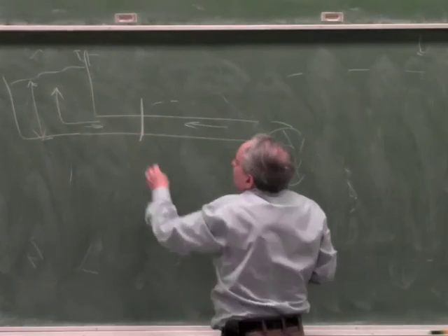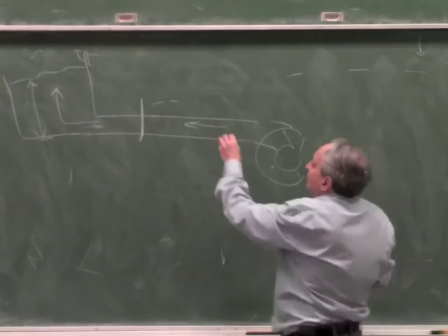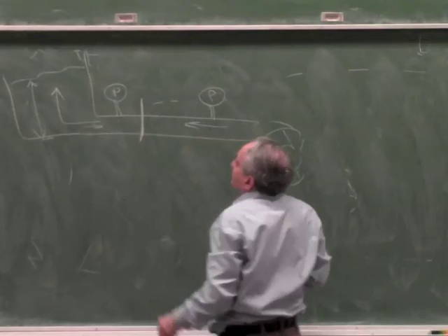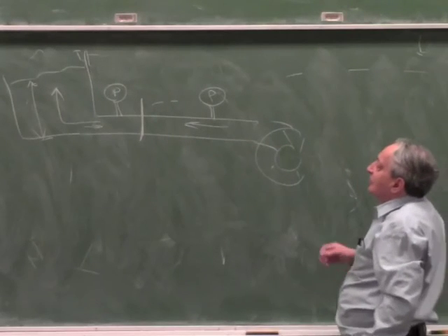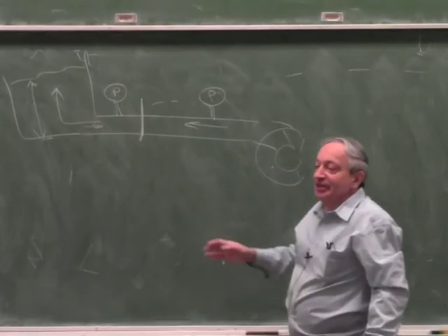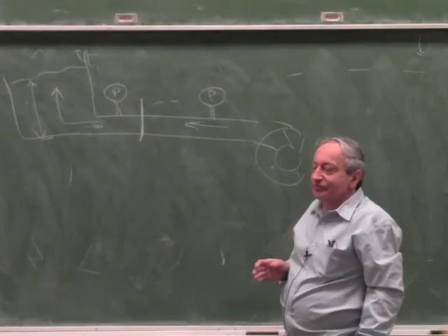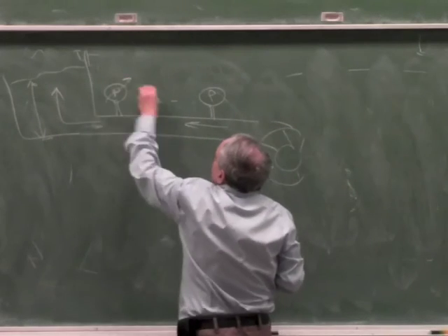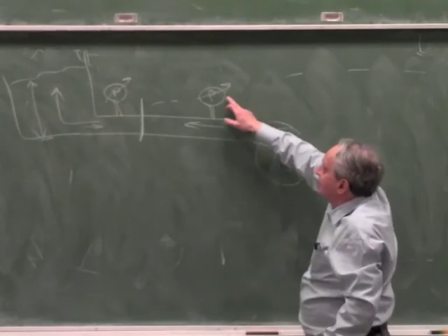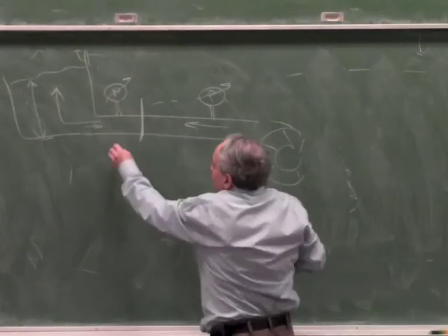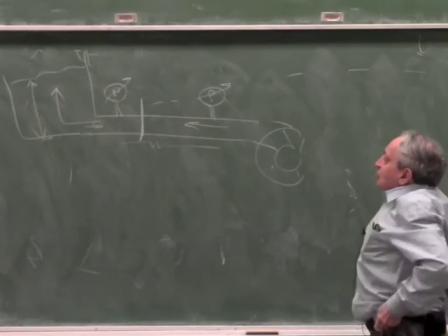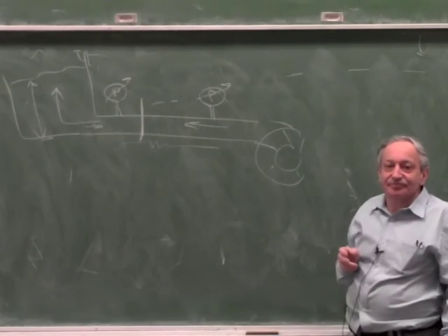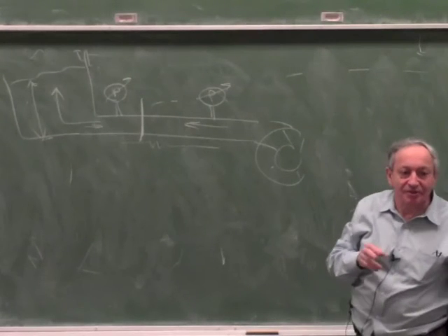If you shut off the water flow suddenly, what will happen to the pressure? So this is P, these are pressure gauges. What happens if you shut off the water flow momentarily? Let's say they were both reading a certain pressure while the pump was working. This one was a tiny bit higher than this one, because a pipe is a bit like a resistor. But now you shut off the water flow suddenly. What will happen to the two pressure gauges? One will rise and one will drop.